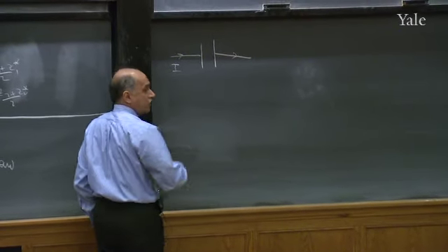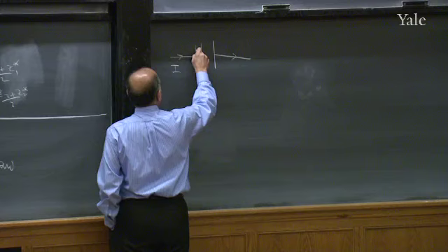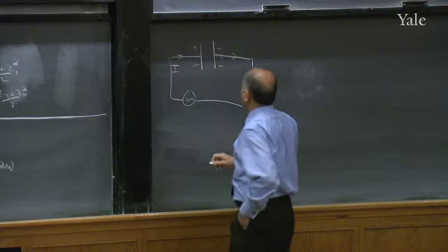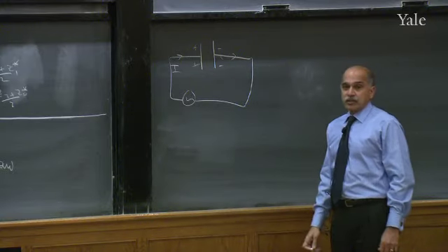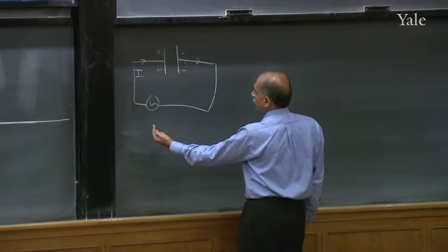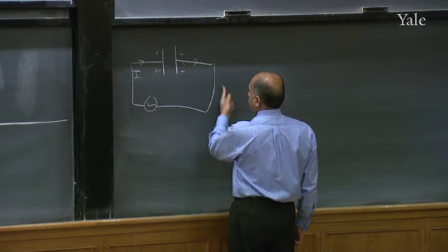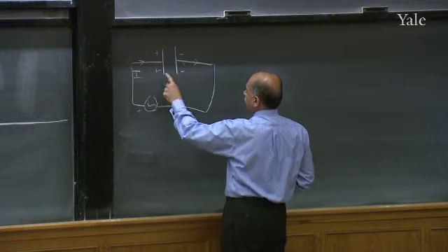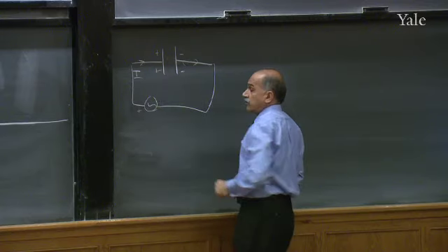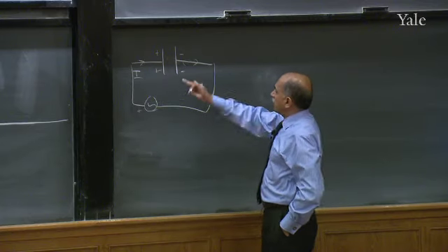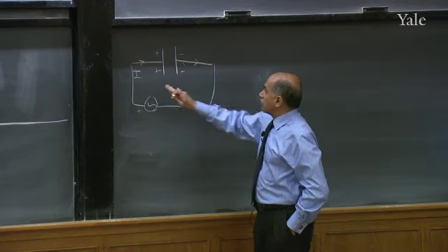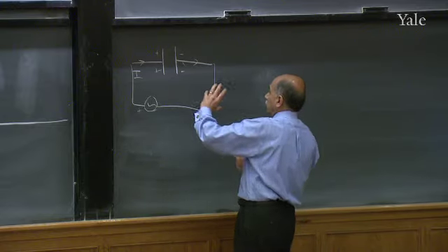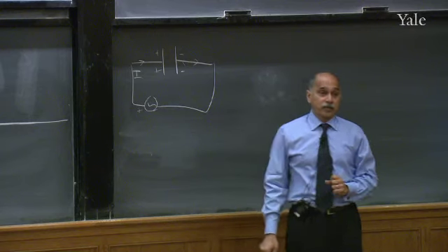When I say flowing through a capacitor, I hope you know what it means. I want you to be very clear about this. Suppose you connect it to some AC source. Nothing really flows through the gap in the capacitor. It's not possible. What happens is, for a while, plus charges rush here and minus charges rush to the other plate because that's the polarity of my AC source. Later on, it's reversed. Then minus charges go here and plus charges go there. So there is an alternating current in the circuit, but there is no current flowing right through in one sense. But there's nothing to keep it from going this way and that way and this way and that way because they don't have to jump the gap to do that.